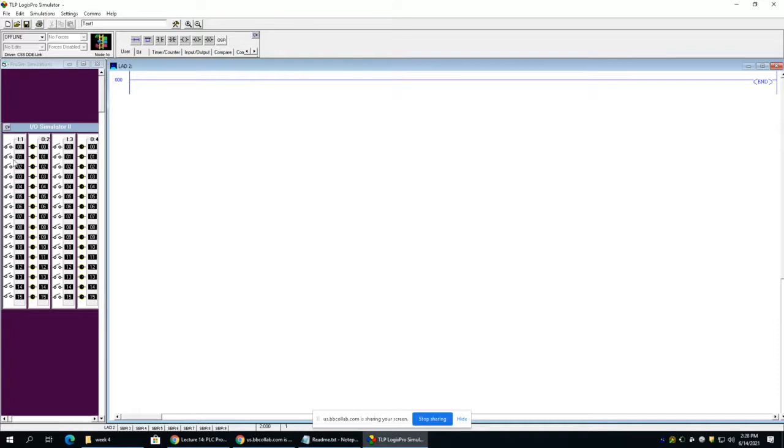The other thing to notice is that I have these switches over here. You see, this starts at 0 and goes all the way to 15. These represent those screw terminals that I talked about, and they're showing you they already have the switches pre-wired for you. So this represents hardware in your simulator, and for each screw terminal, there's an LED right here. That LED just lets you know whether a switch is on or off. See, if I click that, this lights up red, I know it's on. And then I'll see the same thing over here when I have an output that's on.